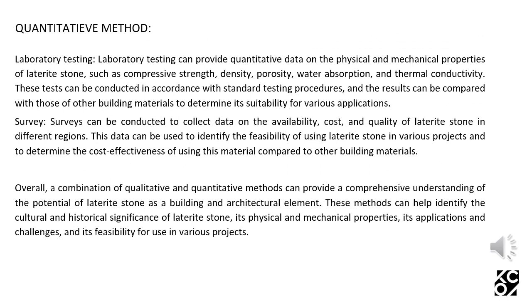The quantitative methods include laboratory testing. That is, laboratory testing can provide quantitative data on the physical and mechanical properties of laterite stone, such as compressive strength, density, porosity, water absorption, and thermal conductivity. These tests can be conducted in accordance with standard testing procedures, and the results can be compared with those of other building materials to determine its suitability for various applications.